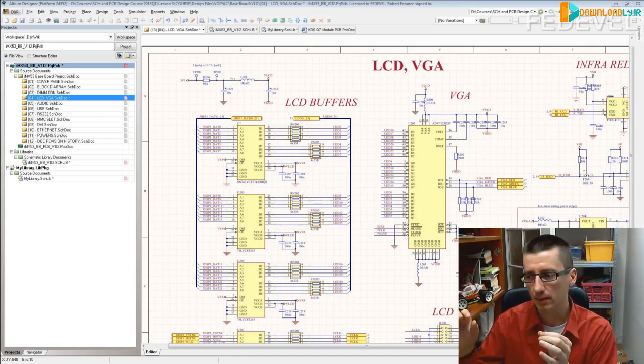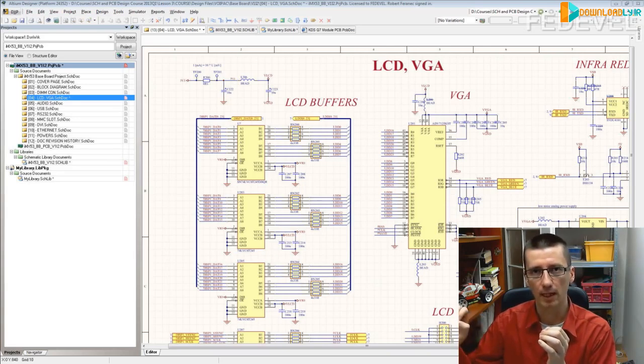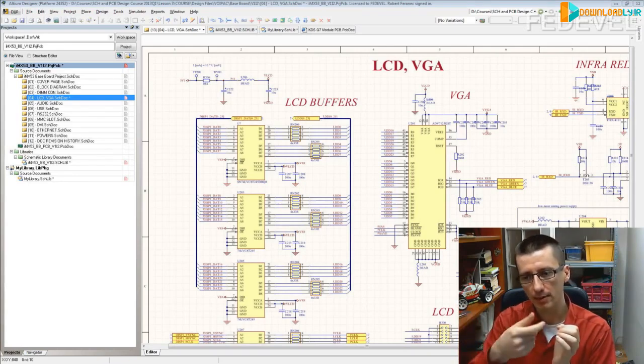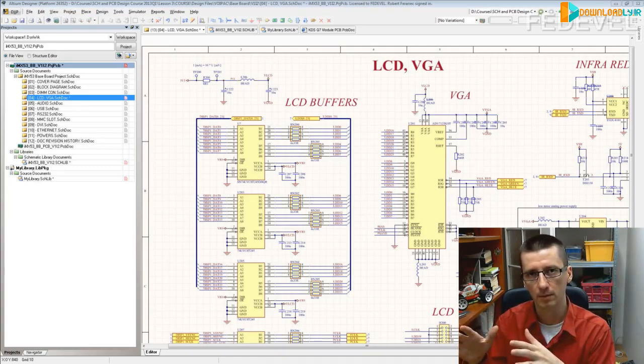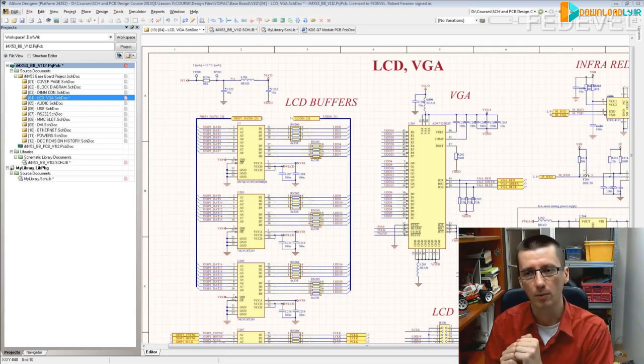And what was happening, the noise went out through the cables. So when we were doing EMC and EMI measurement, the noise coming out of the cables was quite high. And when I placed all the 0 ohm resistors, it disappeared. And in the last design, everything was just fine, no problems.